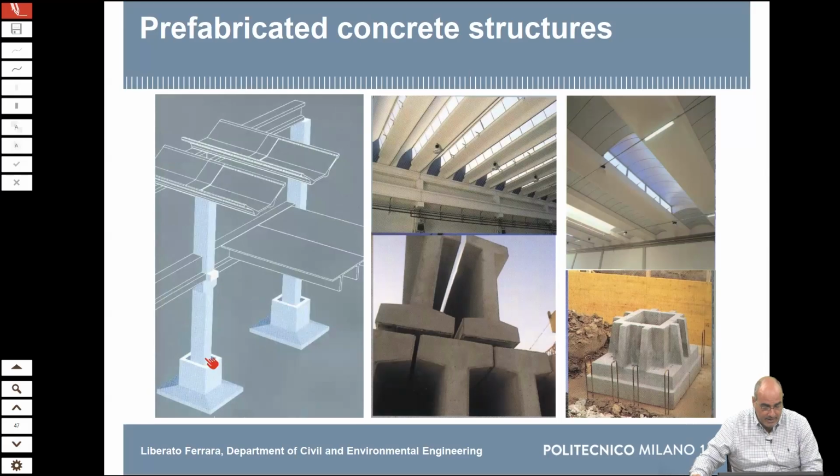You see, for example, this is a layout. It's an architectural drawing from a two-story building. These were typical. Now they are not so common. They were typical foundation elements. They were precast as well. Well, they were very effective. You brought them, you put the column inside, there was some centering mechanism to help, there was a pin, and then you completed pouring, generally with shrinkage compensated concrete. So this was very effective in guaranteeing the fixed edge at the bottom of the column.